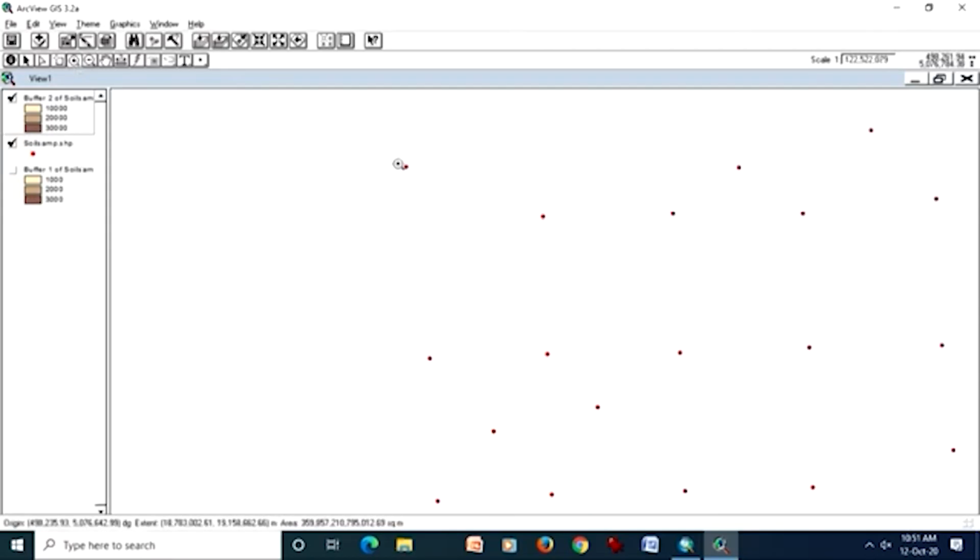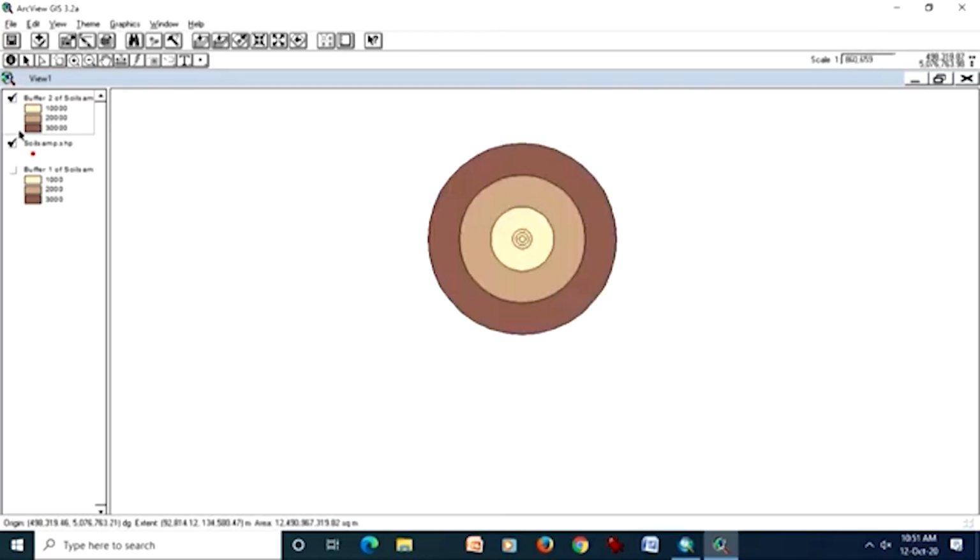Depending on what distance we are giving, there will be multiple buffers around each input point which you are seeing here. So each point has multiple buffers, because earlier we created 3, and now, giving different possibilities, we have created 3, so there are more buffers now. So multiple buffers can be created. What is the use of multiple buffers?